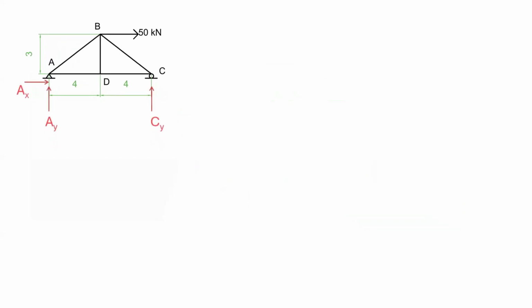Actually, the process that we're going to use is from the joint method. But what we're going to do is not solve the reactions first. Meaning, we will remain them as unknowns so that we solve them simultaneously with the other internal members.